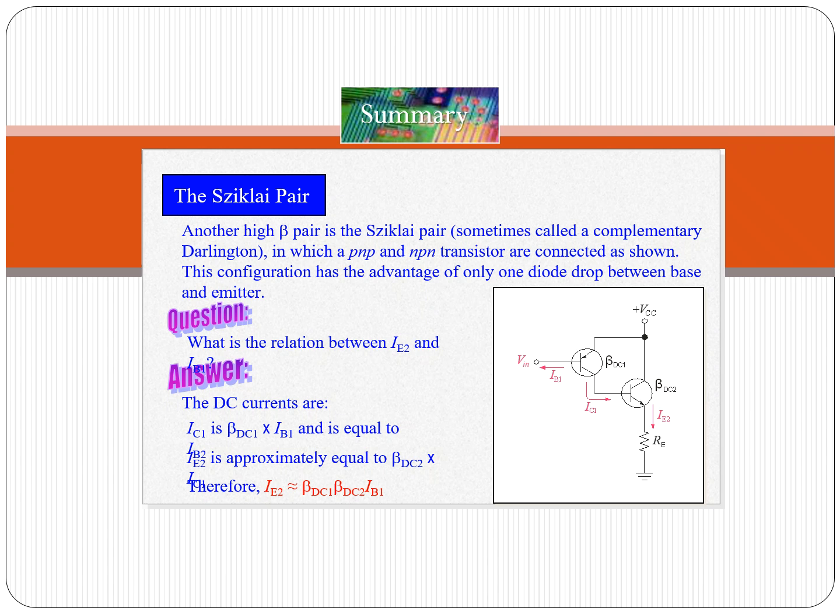The first DC beta and the second DC beta, multiply them together times the current at the base. And what's going to happen is you're going to have less voltage drop. This is helpful when supply voltage is very limited. You're going to have more thermal stability in some designs. And this works well in complementary push-pull amplifier stages. So if you want the gain of a Darlington but a lower turn-on voltage, the Sziklai pair is your go-to. It's elegant, efficient, and another powerful tool in your analog design kit.